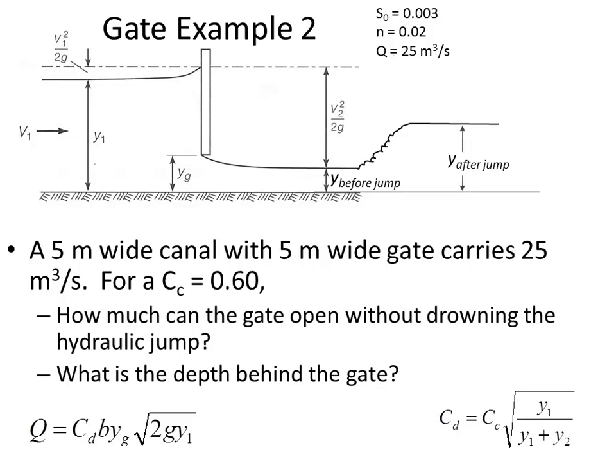That's right. So we've got the channel bottom, and critical depth is sort of like a dividing line, y sub c. Any depth that's less than the critical depth, this is the supercritical zone, and this is subcritical. So if the normal depth is up here, and that's what we've got, y sub n is greater than y sub c. Our depth is up here, and so that's deeper than this dividing line, so we're in subcritical conditions. So y sub n is greater than y sub c, therefore subcritical.